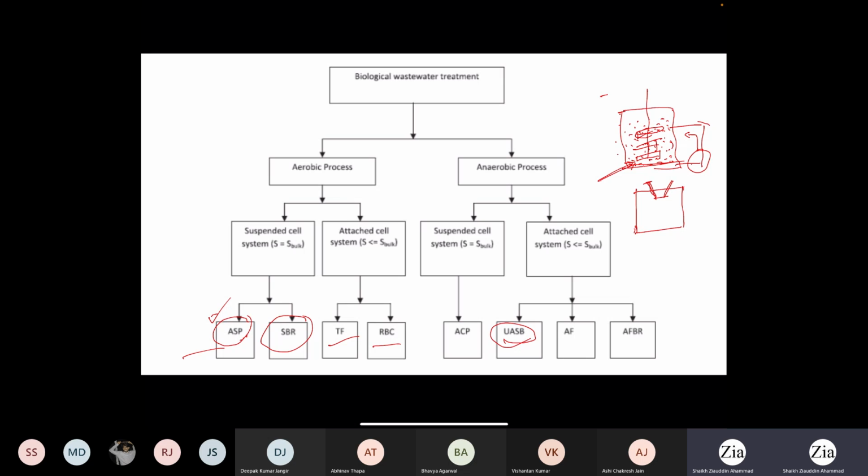Only thing is they will not have the extended shaft and other impellers mounted on them. They will have only this much portion, and it will agitate the liquid in such a way that it helps the surrounding air to get dissolved in the liquid, and also it will create agitation so the liquid has circular motion. So essentially the mechanical surface agitators are used for aeration plus maintaining this recirculation in the liquid.